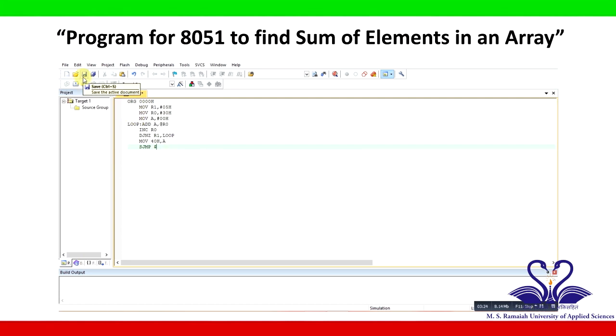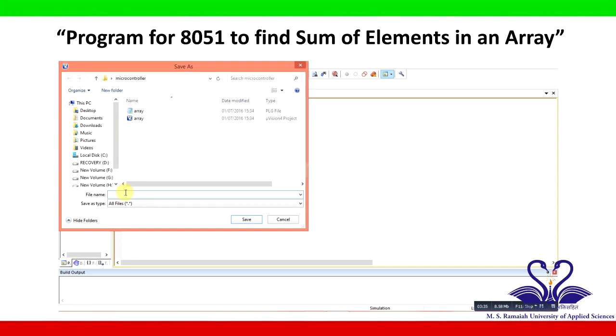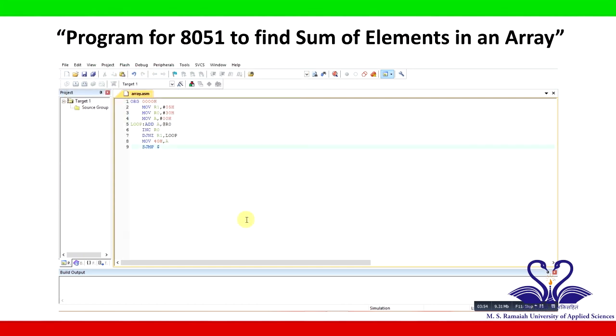Once this program is written in the text editor window, go to file, click on save as, and give some name to your file, array. I am giving the same name, array.asm. You can give any name for your file, but the extension should be .asm. Once the file name is given, you save. Then you have created a new project, created a new file, already written the program and saved it with some name.